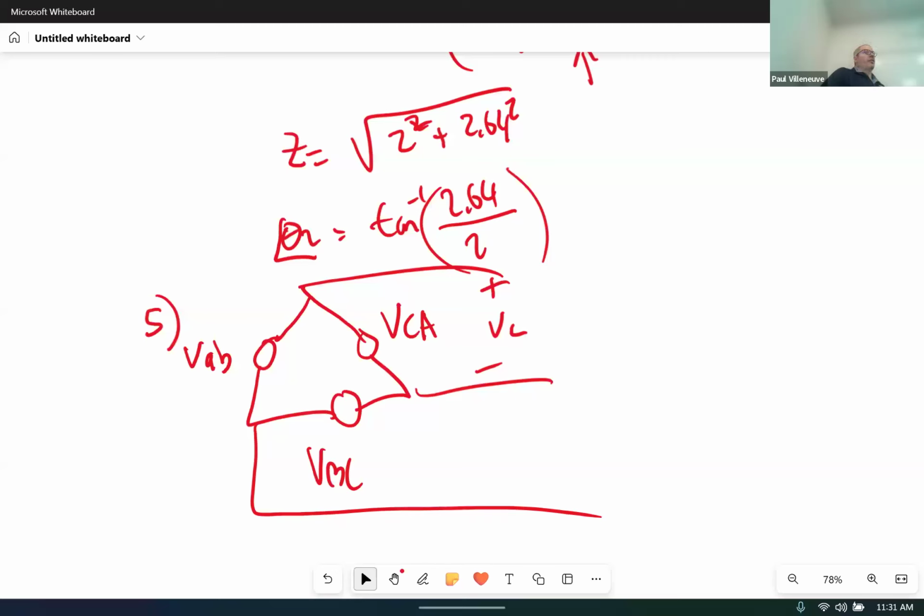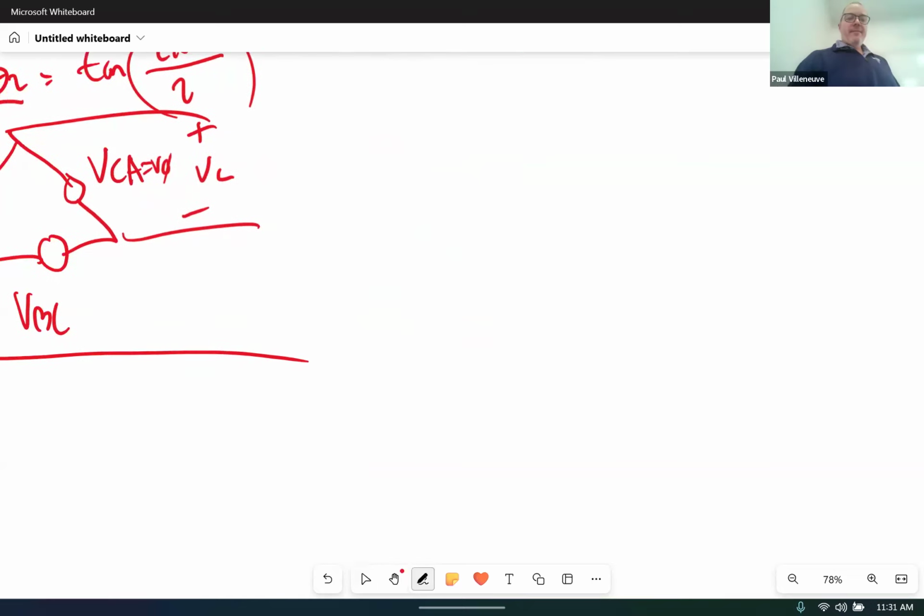What are the phase voltages? It's the same voltage as the line voltage in the delta, right? Remember that table we put out? Line and phase voltages are exactly the same. So both of those were as shown. And then the phasor diagram. That's it. 15 points.